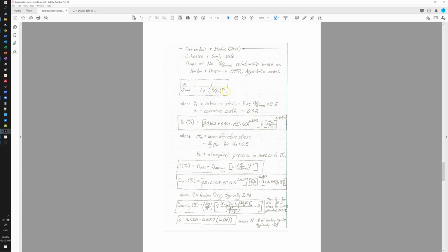And in these files, I also give you a little more detail on the Stokoe model, on how to establish those empirical correlations on G over G max and the damping ratio. He has a lot of resonant column data, because Stokoe has a very well-run lab at Texas running resonant column tests, and he got a lot of projects from nuclear plants around the United States.